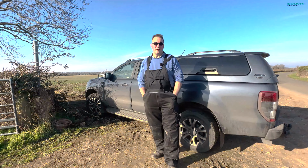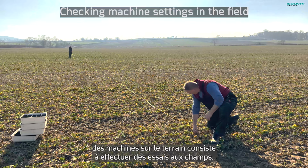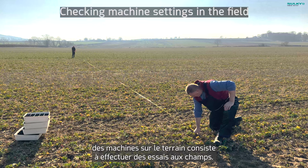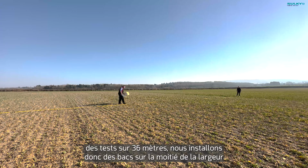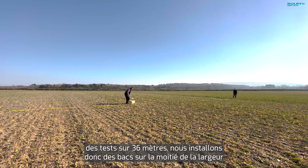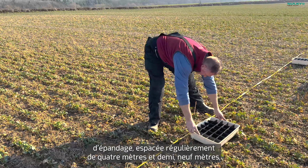One of the processes we go through on installation of machines in the field is to carry out a tray test. As you can see in this example here, we're testing over 36 metres. So we set our trays out over half the width, evenly spaced, 4.5, 9, 13.5 and 18 metres.